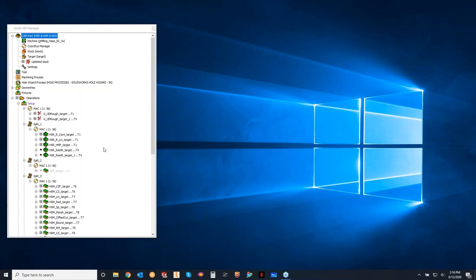It's limited in that you can't choose some of the geometries, but a lot of the stuff you're going to change on the fly on the shop floor doesn't even need that geometry. So that's one benefit of it. In addition to the fact that you can still actually do simulations. That's pretty good in itself. Because normally when you make those hand edits, you don't get to see the results of that. But when you make that change and you want to see, let's say you've added a proper clearance to the holder or a fixture collision detection clearance, and you want to see what effect that takes inside, let's say, Solid Verify, you have the ability to do that on your low-grade computer.